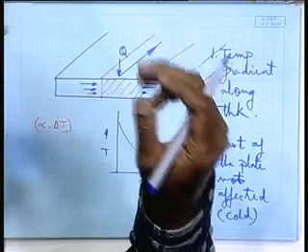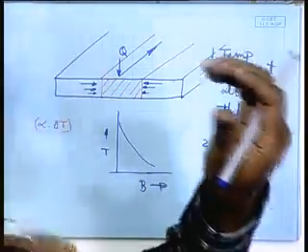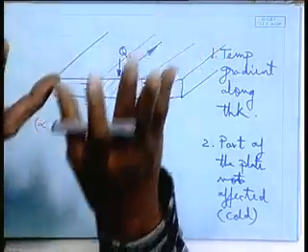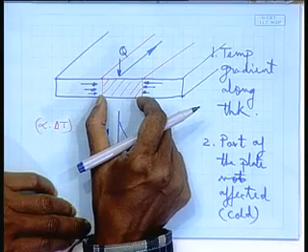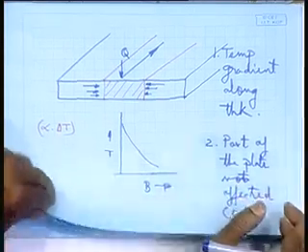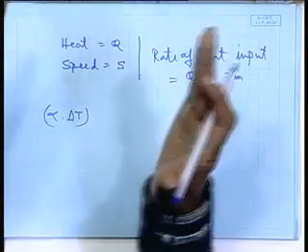And then again you may recall we talked that thermal forces will be generated. The plate is hot, so the elastic limit has got lowered, yield point stress has reduced, and then it will also be undergoing so-called contraction, right. So all these things will be happening to this zone which is getting affected due to the heat, right. So one of the aspects that will happen is it will be shrunk.